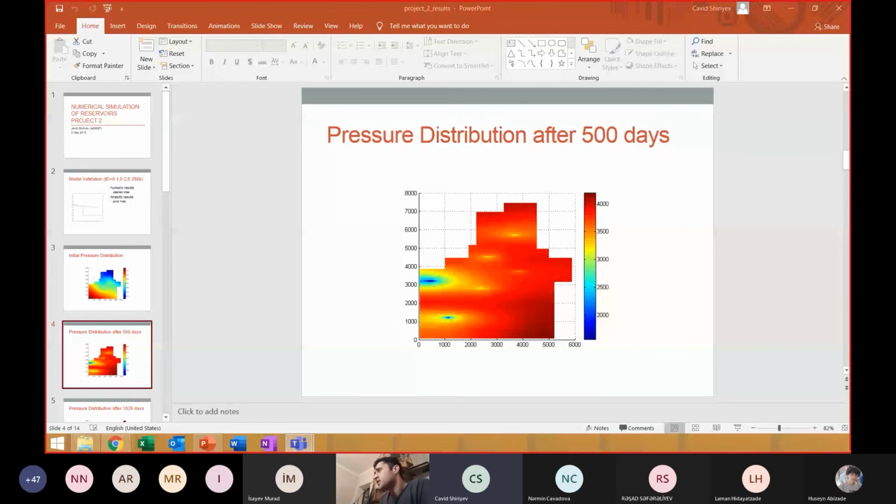So the other question is in which dimension, 1D, 2D, or 3D. As I said, our numerical solver is going to be full 3D. But for demonstration purposes, we are going to write everything in 2D. 2D is not much different than 3D. If you write everything correctly when you're coding, you can just modify it a little bit, and then the simulator will be a 3D simulator as well. The modification only comes to the transmissibility matrix that we are generating for the solution. We are going to write it in such a way that switching to 3D will be a matter of seconds.